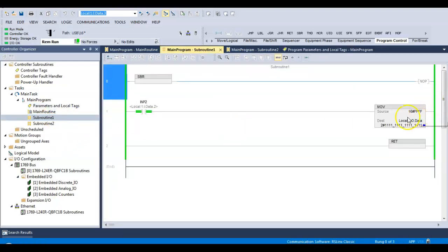But when you select the output, just hit enter when you get to the data. Don't hit the little scroll button and go down and select 0, 1, 2, 3, 4, 5 and select the individual bits. If you do that, you grab only the individual bits instead of the whole 16-bit output. I'm not using a tag, so that's why I don't have it in my tag table.